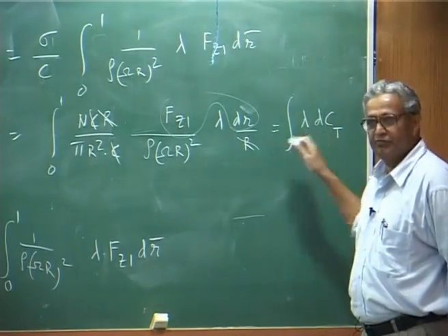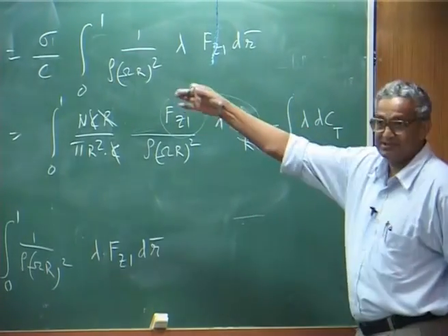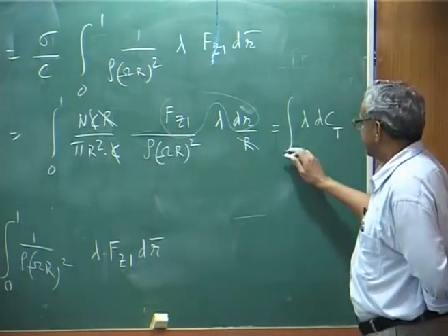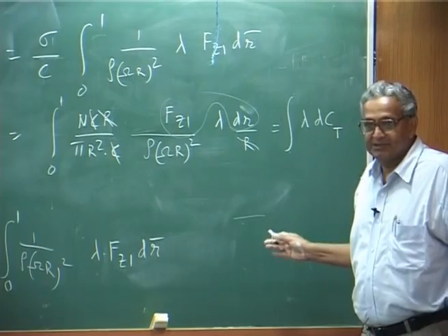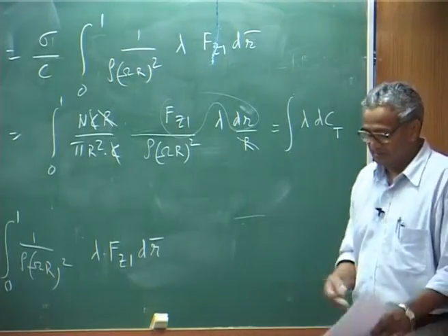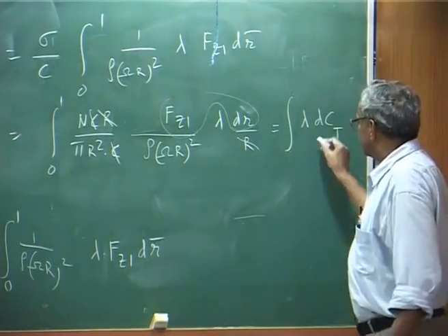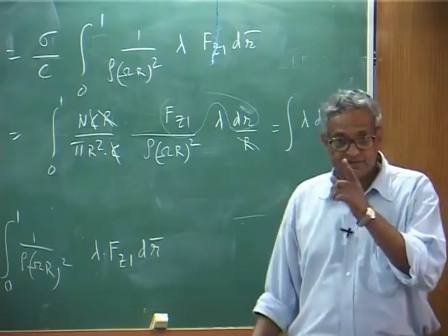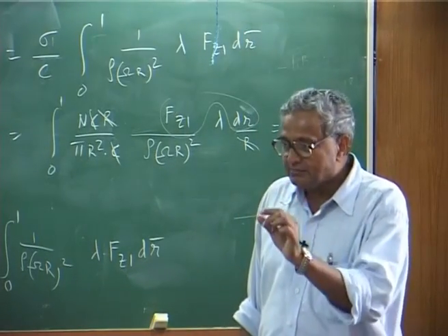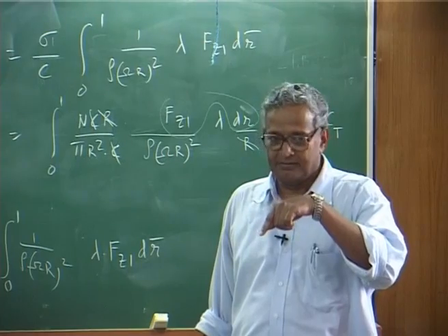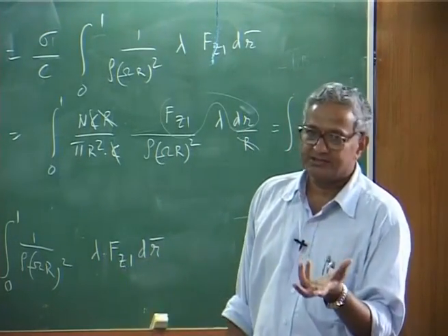If you want to do this, you have to do an averaging over the 2 pi, that is why that averaging is always included. This is over the full disk, because if you average over the entire disk, 1 over 2 pi is always there. So, dC_T, because we mentioned earlier C_T is varying at every time, but when you do the averaging you get the mean value of the thrust.